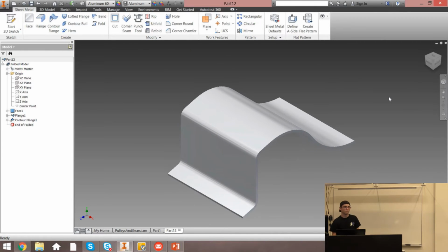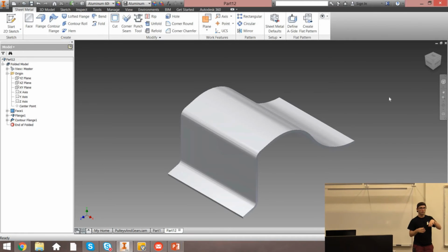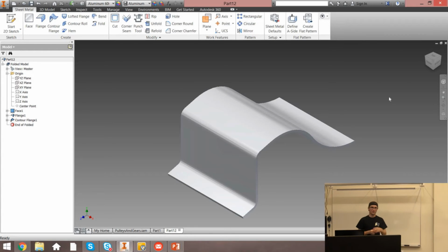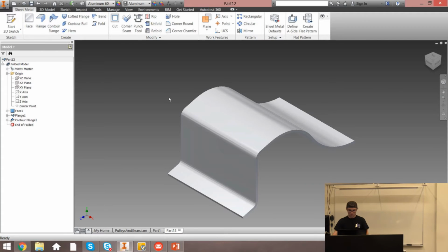Voila. Really, really good if you have some kind of aluminum sheet you're just kind of laying over your robot in some kind of contour. That's going to be the way you want to do it. Way more useful than trying to do flanges or splines and getting it to extrude. All right, those are kind of the main things you're going to do.